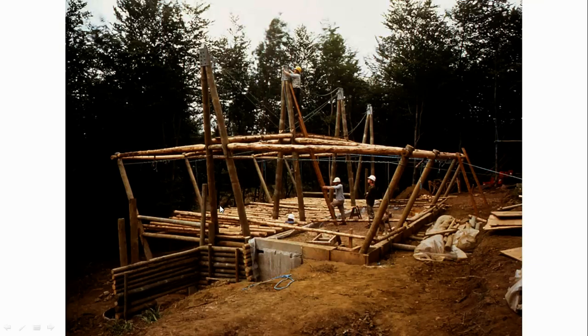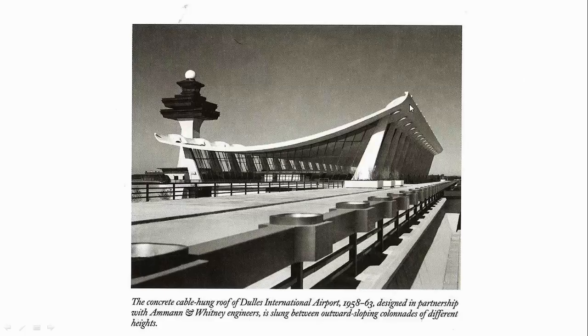There's the real thing. Interestingly, they built it. This is at Hooke Park in Dorset. It belongs to the Architectural Association, and they build interesting prototype buildings down there. And this is one of them. Can you see it's actually a series of A-frames, but the A-frames are carrying tension in these logs here, which are wanting to fall away, aren't they? They're wanting to fall away, and they've been carried back to these central masts. Rather elegant structure, using local resources, using trees that came from Hooke Park.